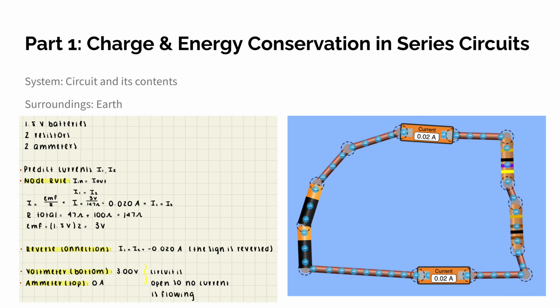For part 1 of the lab, 2 batteries, 2 resistors, and 2 ammeters were used to create a circuit. Predictions regarding currents 1 and 2 had to be made. Using the node rule, which states that current going in equals current going out, I was able to calculate the desired currents to be 0.02 amps. As you can see, the voltages of the batteries were added to be 3 volts and the resistors were also added to have 147 ohms.